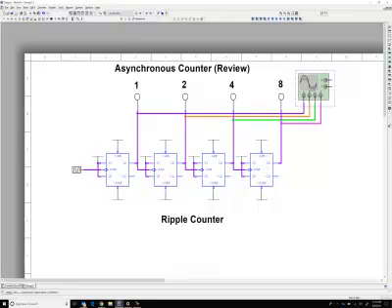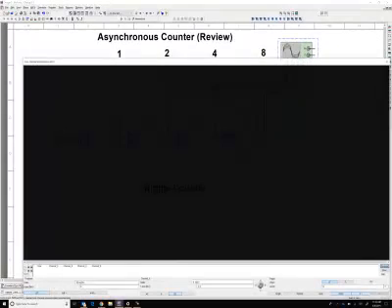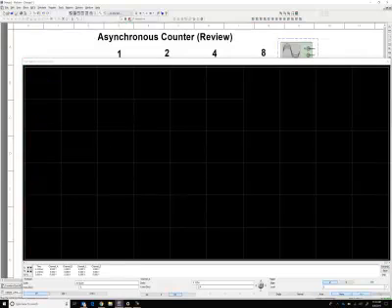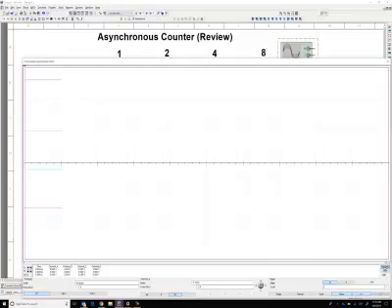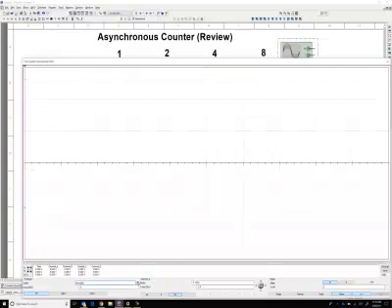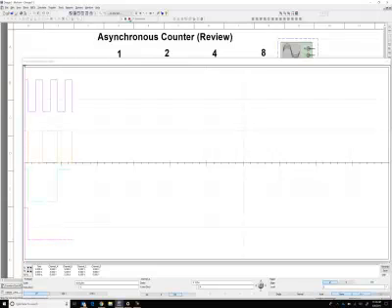If I connect the 4-channel oscilloscope that I can find on my right screen over here, I just connected it and changed the colors of each of the wires so that on my screen I can see them in different colors. I can then open my oscilloscope, press play, and you can see the channels toggling on and off. Now, maybe it's easier if I put it in white. Let me press play again to make sure that my channels are turning on and off. There you go. So you can see that it is counting in binary.